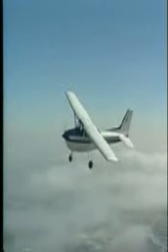Let's look now at a system that provides time-critical flight information. The Notices to Airmen publication and the NOTAM Telecommunications Network are designed to pass along changes in the national airspace system. These changes are either temporary or not available in time to include in other documents, such as the Airport Facility Directory or aeronautical charts. A NOTAM may be classified as either a NOTAM D, NOTAM L, or an FDC NOTAM.